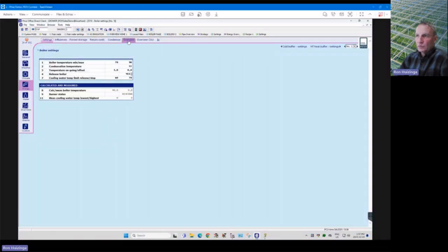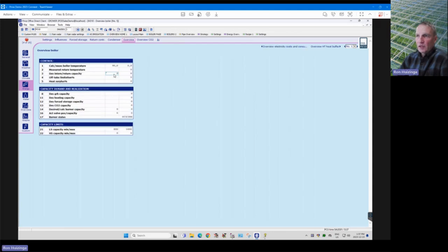So how does it do that? It basically puts a little bit of heating capacity in line 3 here, internal capacity. Internally, it's getting too cold. It's below the 70. They'll put some kilowatts on the boiler there, put it into this line 11, and it'll start the boiler up at a certain number of kilowatts to heat back up to 70 degrees, or plus the offset, like we talked about.